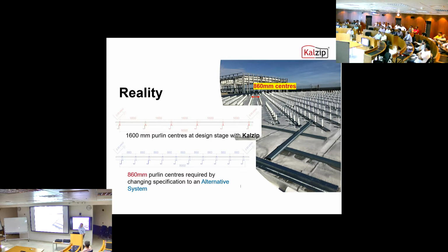It's both, but the VCL provides the air tightness. But it should be covered below the gutter if it's to be watertight. The VCL can be dressed into the gutter. It just depends on what the details are. The Calzip system is watertight. It doesn't let water in.